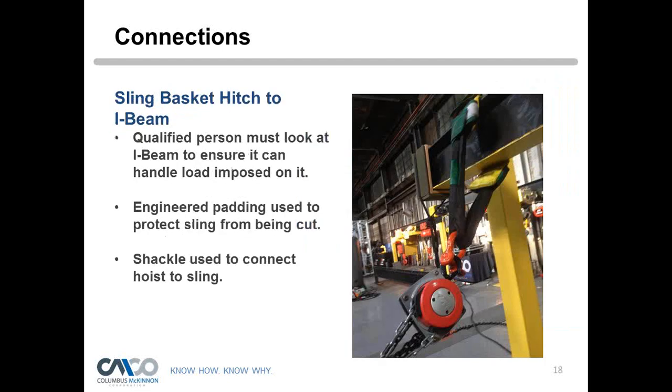So here, what do we do? What do we use, right? In this case, you can see we have an I-beam, and we took a sling and slung it around the I-beam. And what's very important is we need to protect that sling from any surface or edge that can result in damage to that sling.